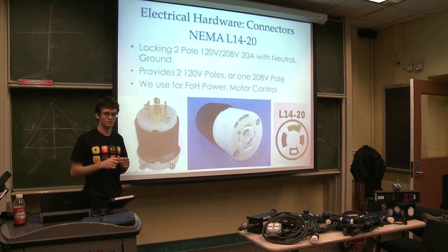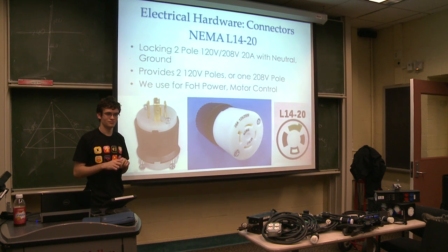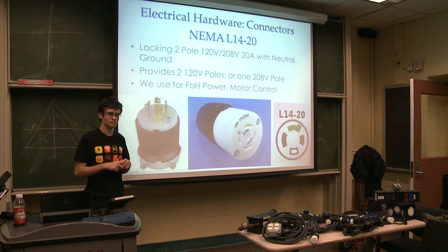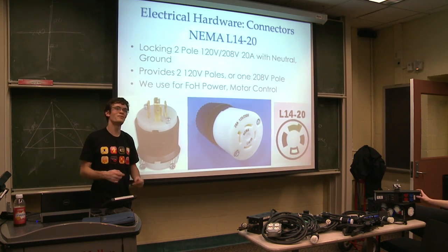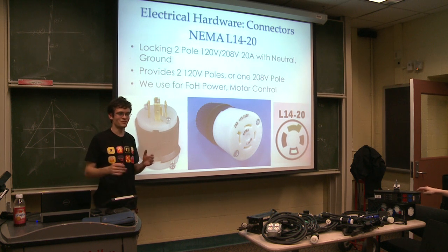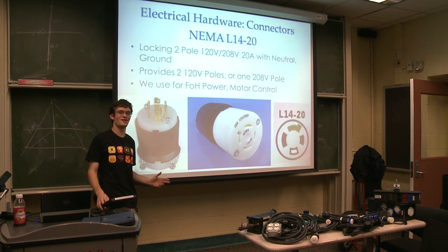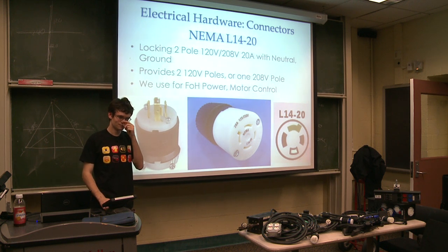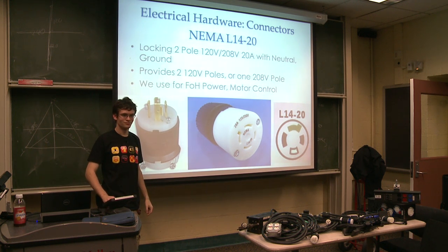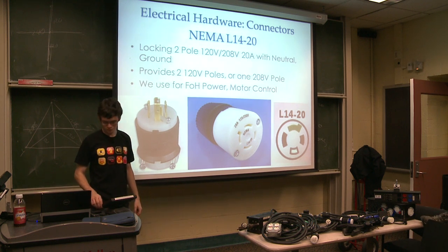Alex, when you split an L1420 into two separate Edison circuits, don't you have like half the... Aren't the phases balanced or something? You want to balance them? It's like this. They're not balanced by any rule other than knowing what you're plugging into them and balancing the current draw. If you don't do that right, you could possibly have an issue with the neutral. You have to be careful not to overload the neutral.